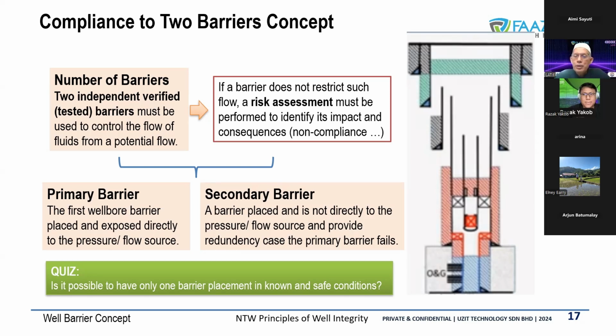And then, of course, when we come in with wireline work or maybe some coiled tubing or whatever, to do the repair job, normally it's going to be a patch. We're going to run a tubing patch where we set the patch across the weak zone.